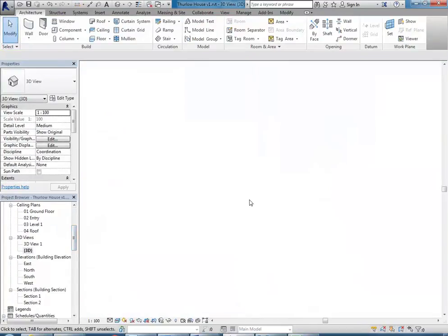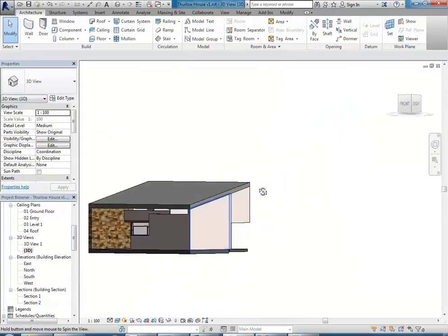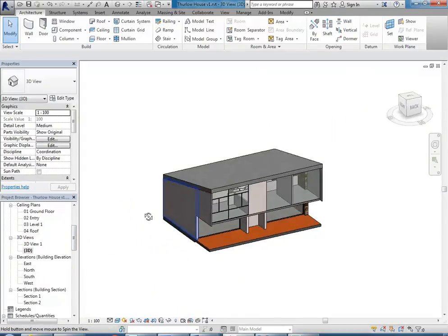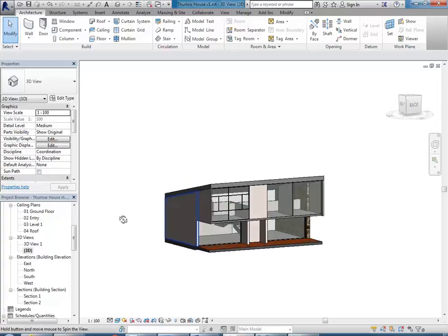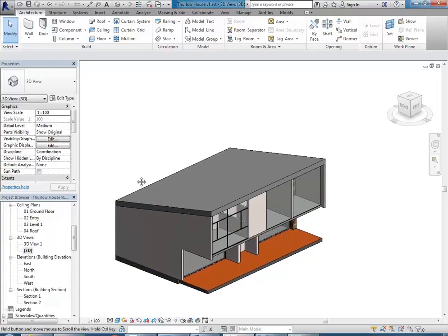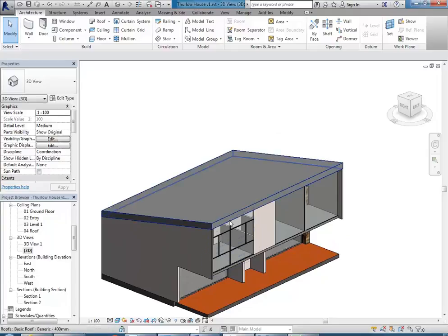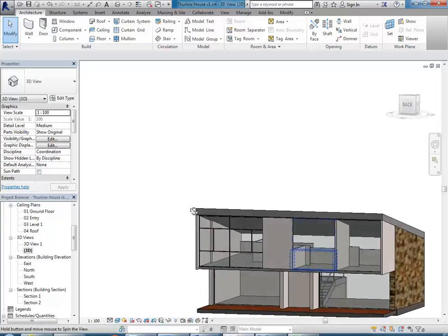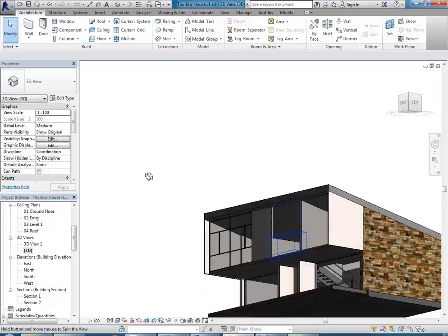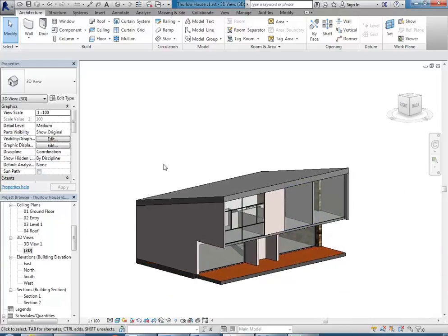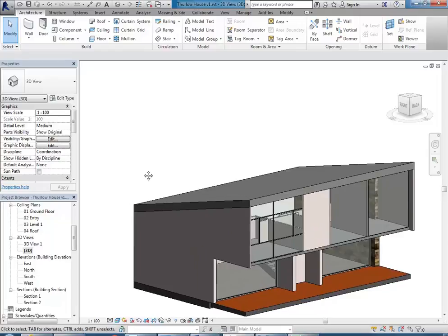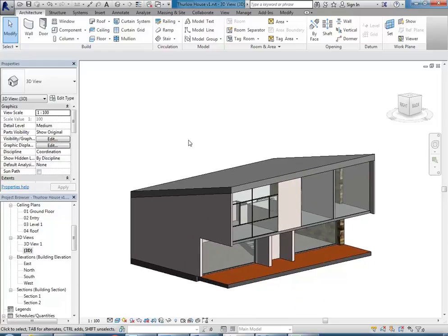So very, very last thing I'll show you there is that if you go into a 3D view, now it might be getting a bit difficult to see those interior walls to make the changes to give them the height we want. So I'll just show you a couple of ways you can set these views up, and you can do this anytime, so you don't need to have all the walls done to do this next step.